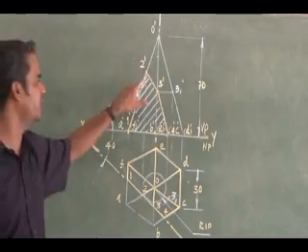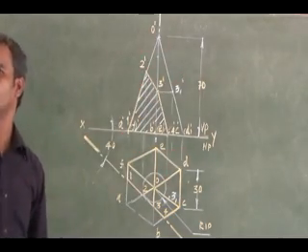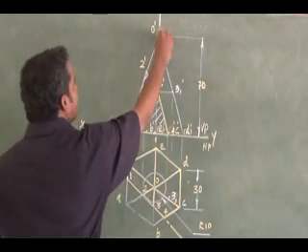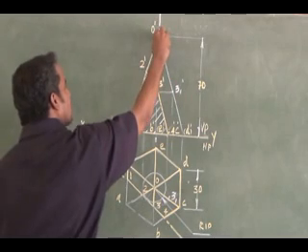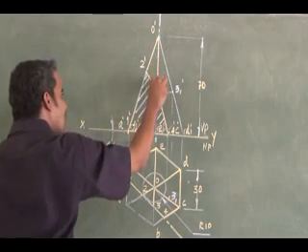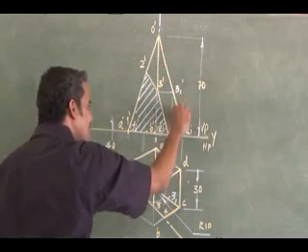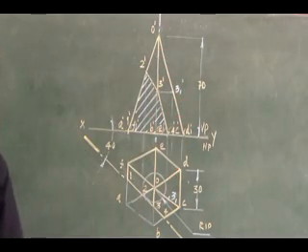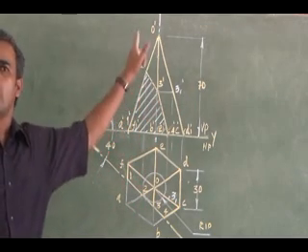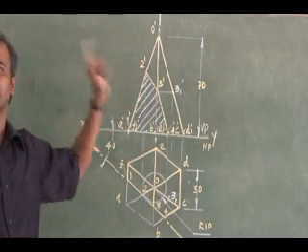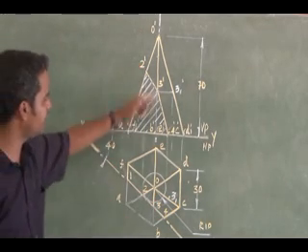Once I have finished the section, the apparent section, the remaining portion also you have to show in your front view. That also you should document. See here, one more thing, the sectional front view is not yet fulfilled. What is missing? Once I have removed this, which portion can I see?